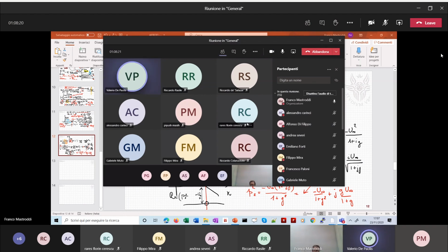Okay? In this case, you introduce an artificial parameter like g. At the end of the iteration, you want to suppress your artificial parameter and relate your K value with the other values like omega and U infinity. So whenever you have converged, you are not making any error, because you have satisfied your characteristic equation and closed the problem. You have satisfied it because you have taken the determinant for each iteration.